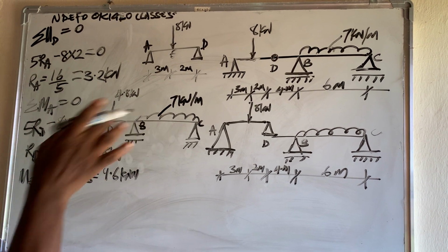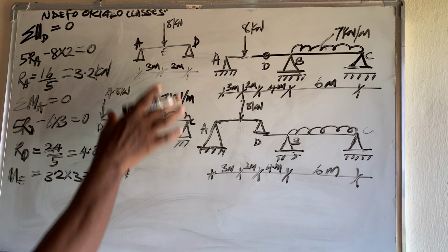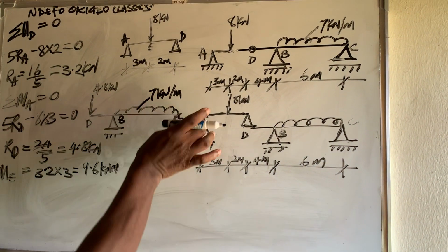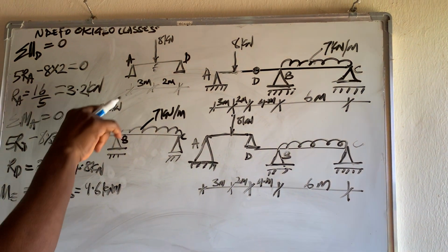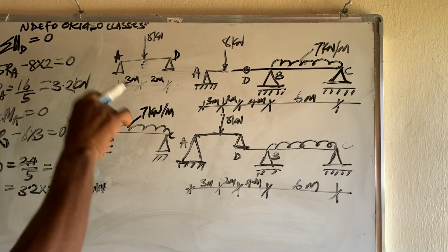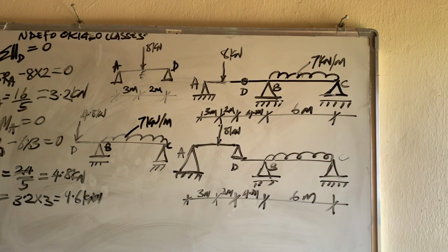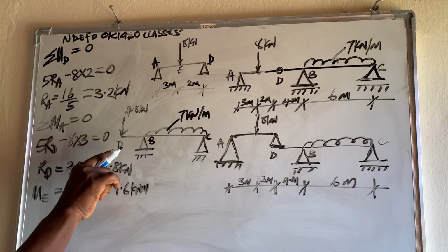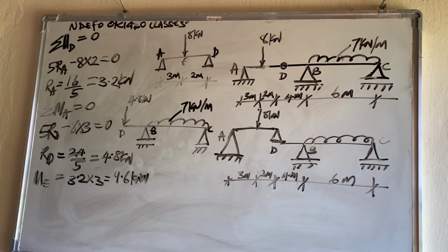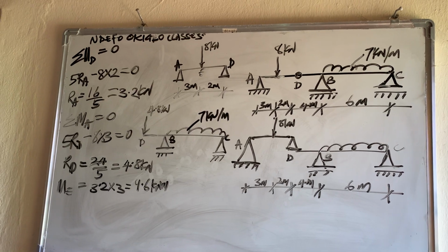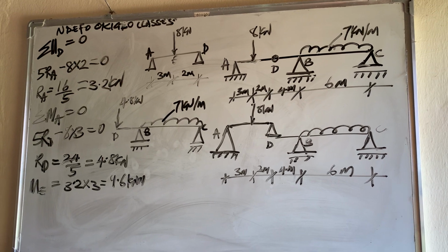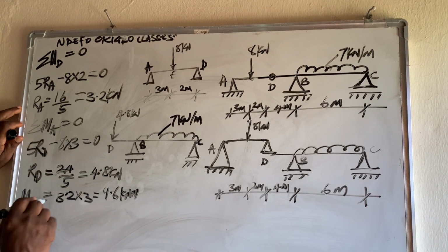So with this, I come to the next beam, the beam BC. I've dealt with AD. I'm working the whole beam, so I'm now at beam BC. At beam BC, I have found a reaction, which is 4.8, the reaction at D. I load it on beam BC, on the cantilevering part of BC, at point D. That's how to solve beams that are continuous but determinate, because there is a hinge in the beam. So to deal with BC now, I want to get reaction.